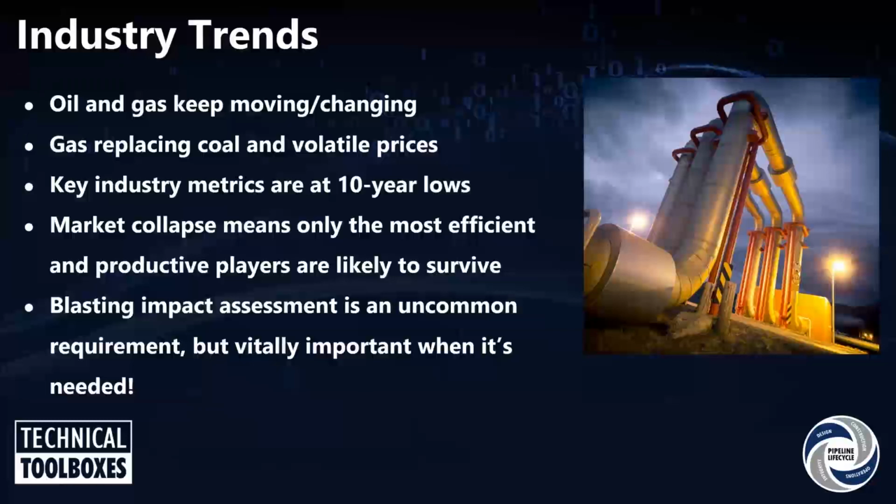Midstream operators must avoid disasters. But the cost of preventing them cannot be so high as to put the company out of business itself. Therefore, engineers have to be conservative in how they calculate ground strain, which adds costs and places constraints on blasting neighbors. They must allow enough uncertainty without overstepping the bounds of cost.